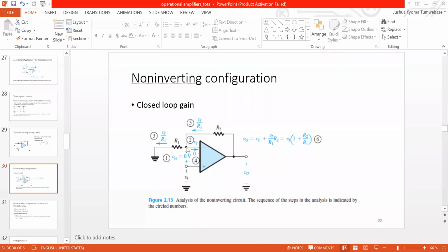No, because for current division, you must have resistors in series. No, current division is for parallel, isn't it? Yes. So you're saying that R1 and R2 are in parallel. That's what you're saying? Yes, I'm looking at that junction as if current may divide, as though they're in parallel.